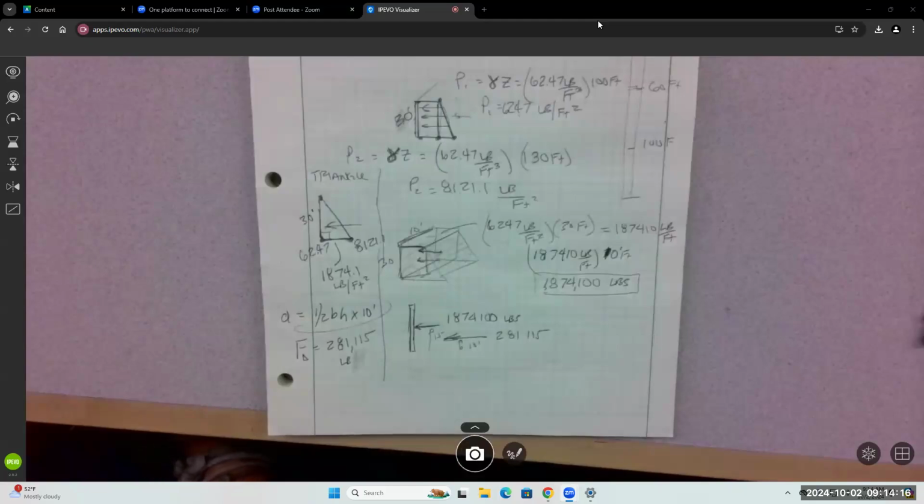Is it the difference between the 2 forces is the question? No, they're both real forces, right? And I have them drawn correctly. There's a resultant force. So if we sum the forces in the X, there's a resultant force. These 2 are both water pressure, they're pushing on that gate. They're acting in the same direction, correct? And they are horizontal, because I made the gate vertical.